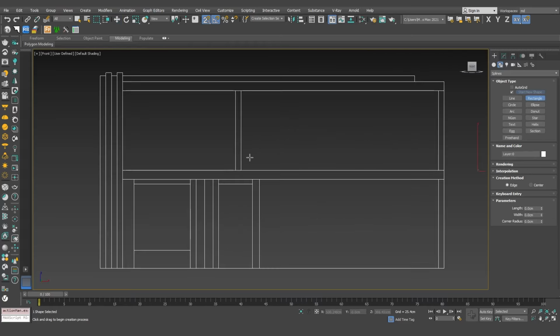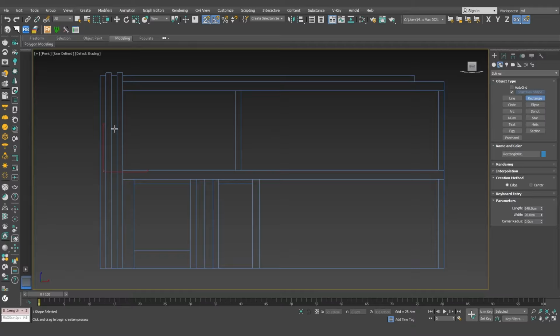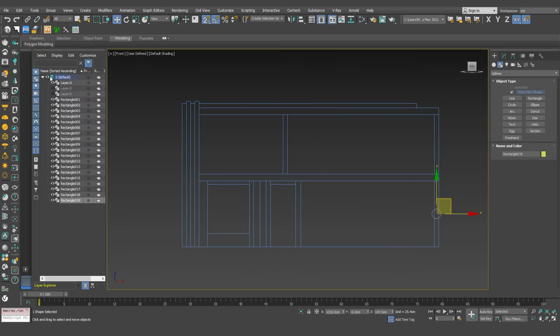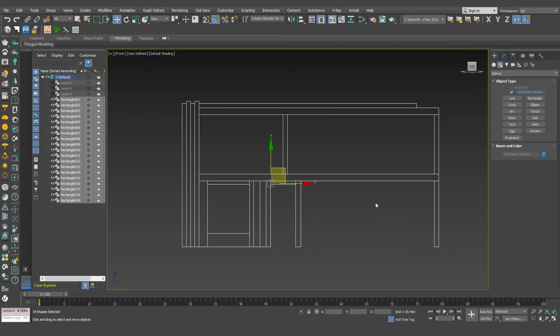Now, I'll start by drawing with rectangle, then apply extrude to them. I'll activate the Layers panel and turn off the AutoCAD layer. Next, I'll select everything and change their color to gray.